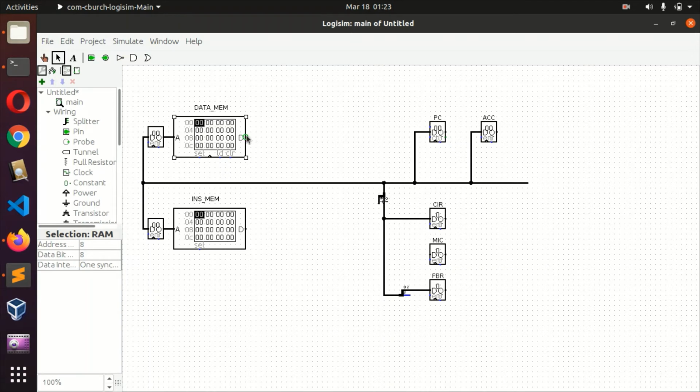So now for this output, let's see. The reason we're able to connect all the inputs of these registers on our data bus, on this command bus, without worrying about anything, is because the input impedance of these registers, or of the logic gates as a whole, is very high.